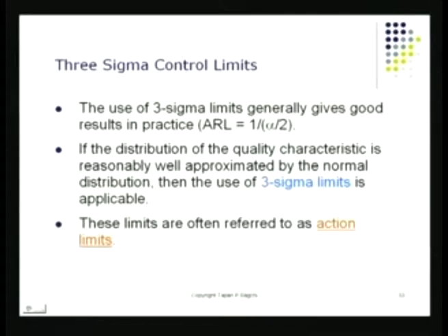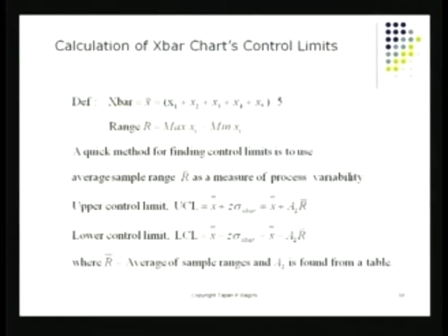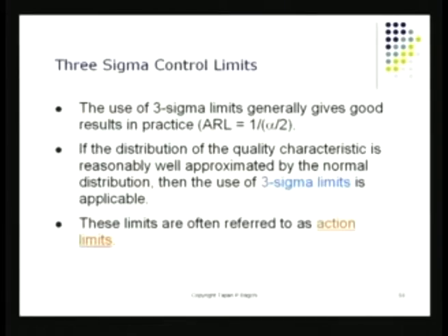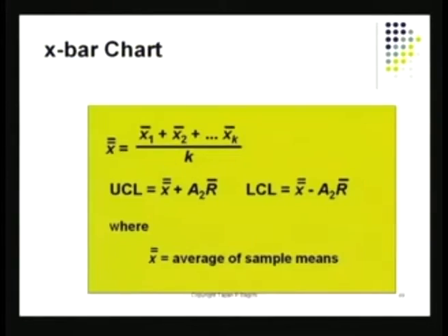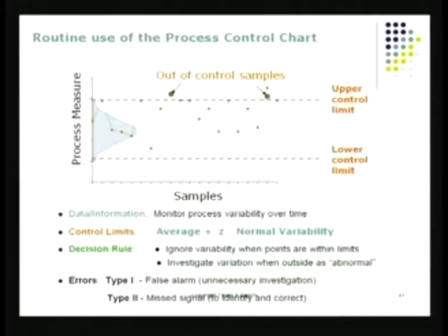But obviously, if the chart shows you that it has gone beyond control limits, and we've got many examples of that, and we'll see some more examples as we go into this. For example, let me just bring up one or two examples. We had seen them earlier. An example is going to be this one. Control limit exceeded. Control limit exceeded. These are going to be instances when you have got to stop the process regardless.